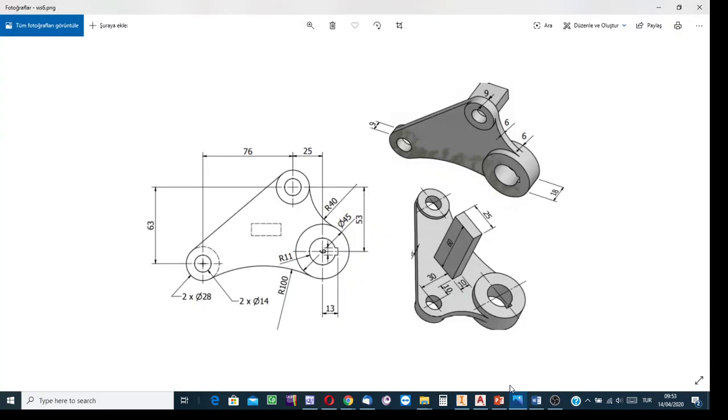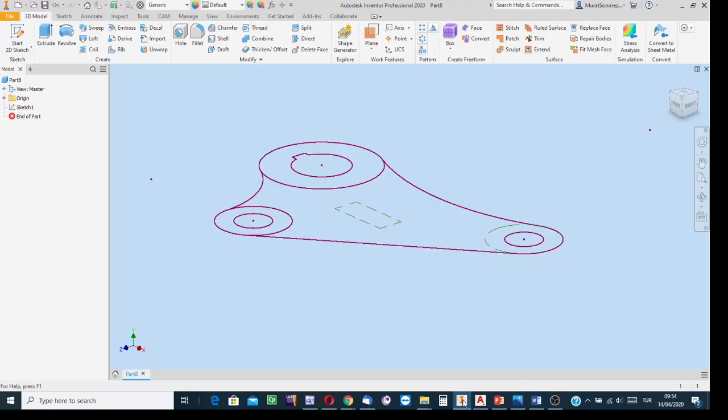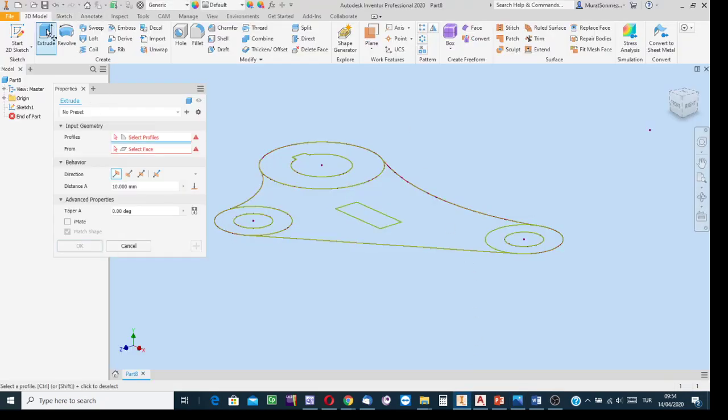Have a look at the geometry of the shape of the object, illustrated in this photograph, the pictorial drawing, and the other. The thickness of the main part is 6 units. So apply the extrusion process. It's a right prismatic feature, so extrusion is the correct process option.